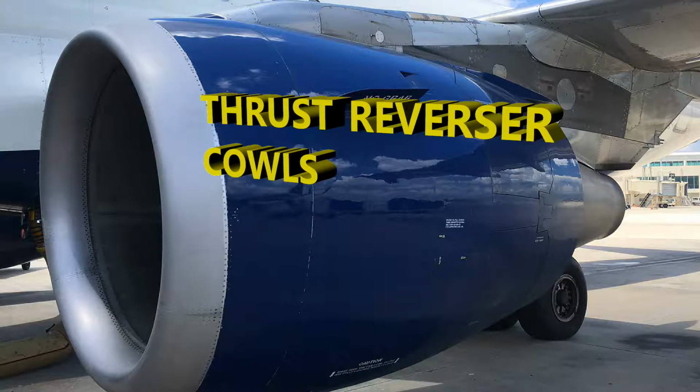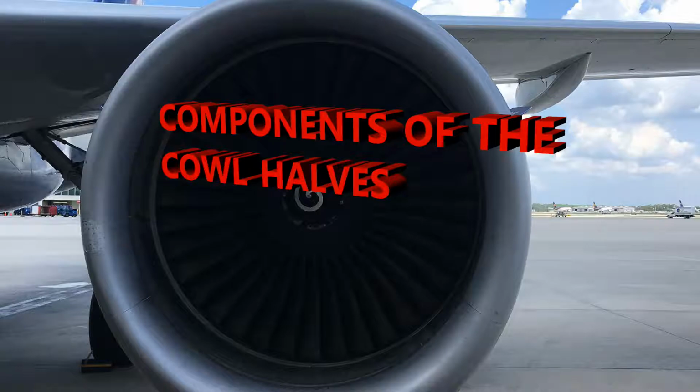But the thrust reverser is made of 2 similar halves, like I said before. Those are your C ducts. Each half has some components. Just be aware of this. Again, you don't have to memorize all of this. There's going to be a latch beam. I'm going to mention the latch beam a little bit later. You're going to have your latches closed, and that's going to lock the halves together and give access to the engine core component when you're doing maintenance. There's a torque box as well. There's an interfixed structure.